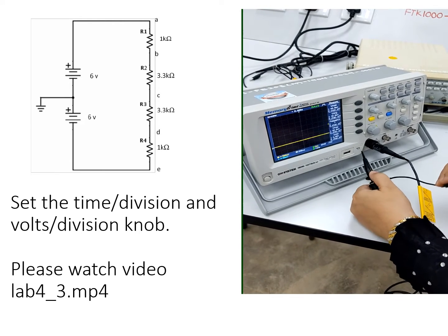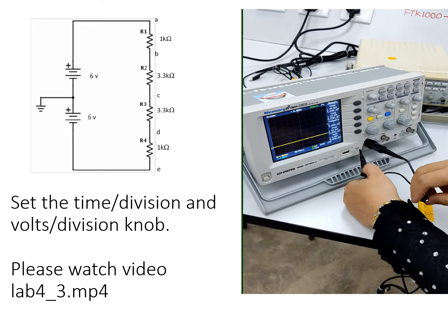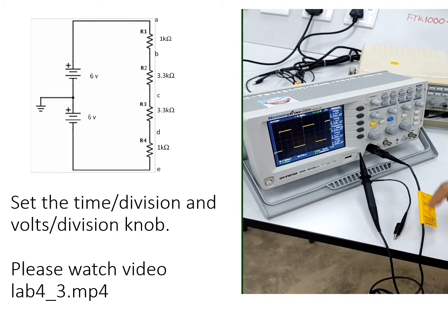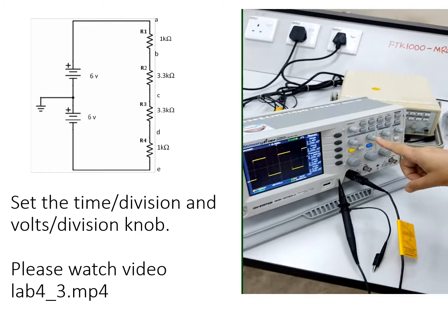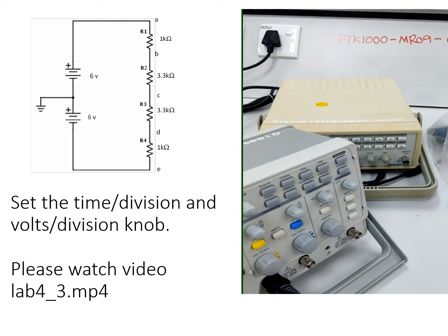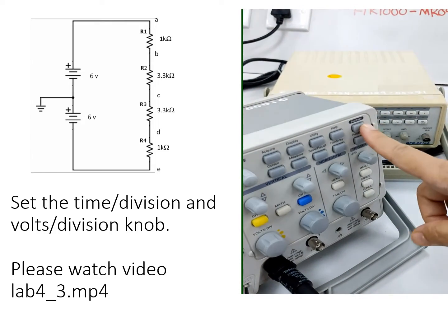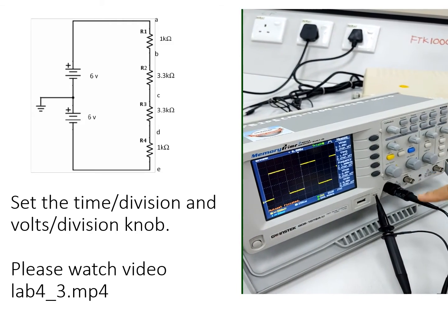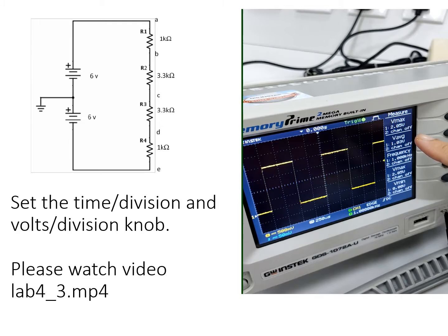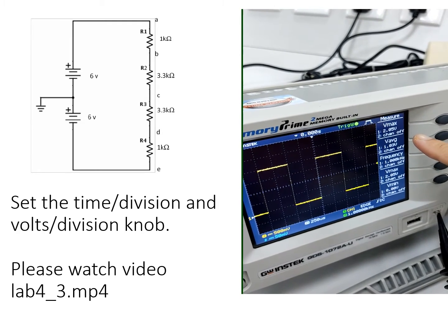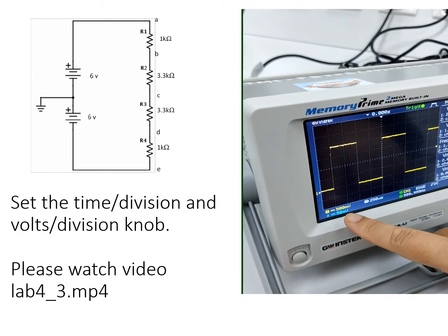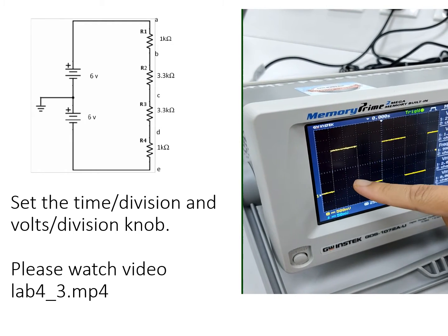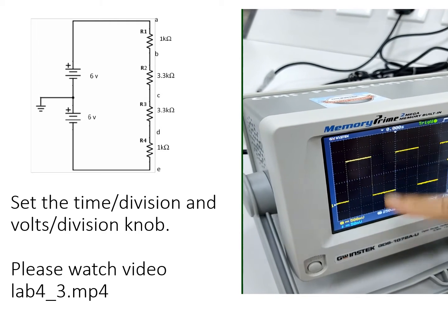First, before we use the oscilloscope, we need to do a calibration. So I connect the probe here, and we press measure. We can see here auto set, and measure. We can see here Vmax is 2.05 volt. You can actually measure from the block here. One block represents 500 millivolts. So here we have 4 blocks, so it is about 2 volt.